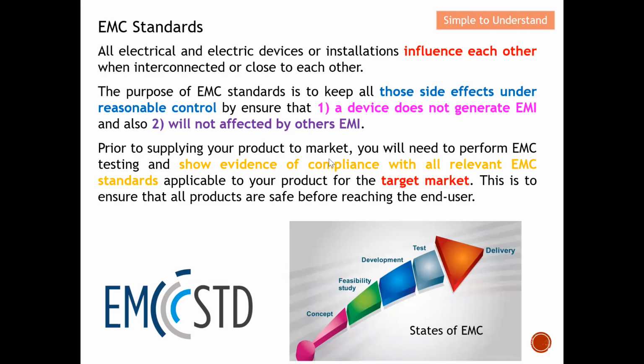Prior to supplying your product to market, you will need to perform EMC testing and show evidence of compliance with all relevant EMC standards applicable to your product for the target market. For example, if you target Europe, you need to comply with all the EMC standards set up by Europe. If you target the US, you need to ensure compliance according to the FCC standard. Why do we need all these EMC standards? This is to ensure that all products are safe before they reach the end user.